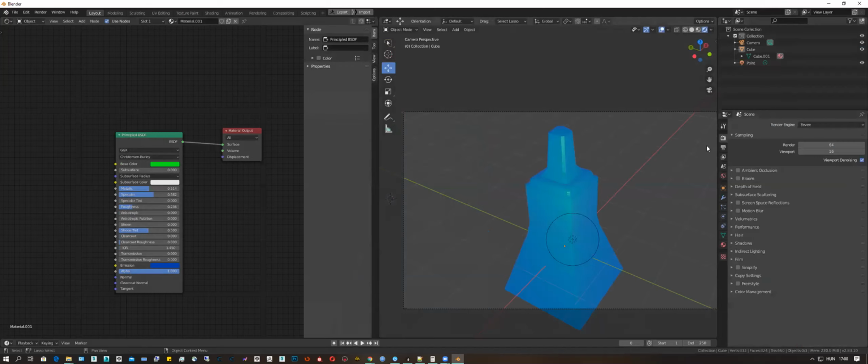Two types of renderers we use, Eevee and Cycles. Here in the right panel, you can click render properties. This is this camera icon, and in the upper right corner you see Eevee is set up. This is real time. It's basically a game engine, actually, or similar to a game engine, and here you can choose Cycles.